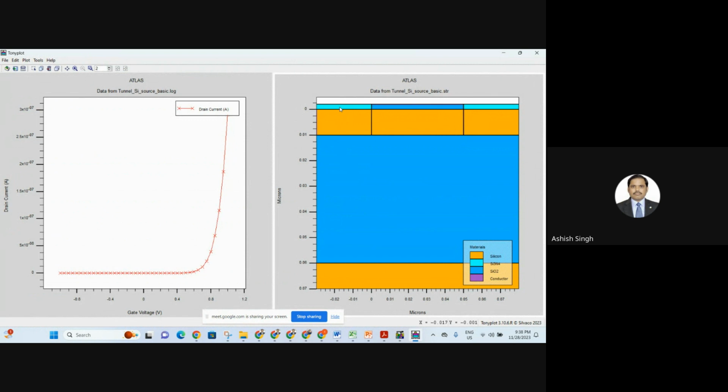In place of air, you can write Si3N4, no issue, or directly write air. You have to make it rectangular anyhow. You cannot make a cut point, lower part and then upper part like that. You cannot define that in Silvaco. This is a disadvantage of Silvaco, if you want to call it that.